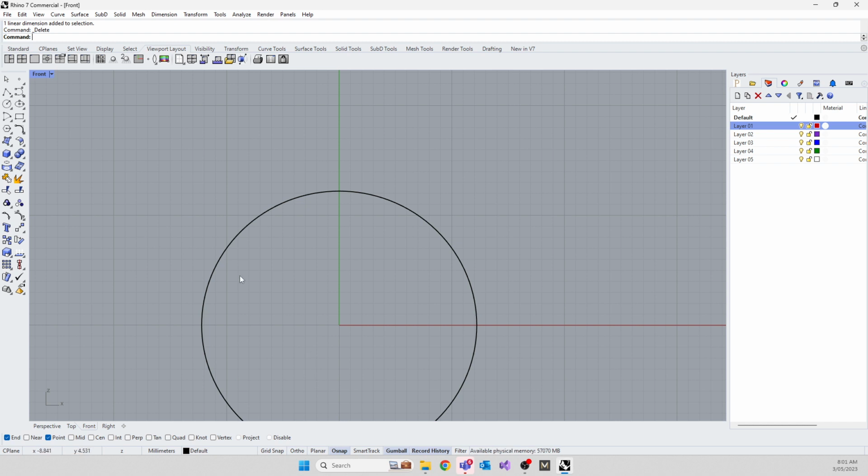So when I draw a line, I'm going to start at 0, the middle of the world. You'll see that it just moves as I move my mouse. If I hold the Shift key down, it'll snap. So the next snap is straight up, the next snap is 45 degrees over, next snap is 45 degrees over. If I'm not holding the Shift key, I can move anywhere I want. Hold the Shift key, it snaps it into 45-degree increments. My line has to be straight because we click the ortho. You can see as I'm pressing the Shift key, ortho turns on and off.